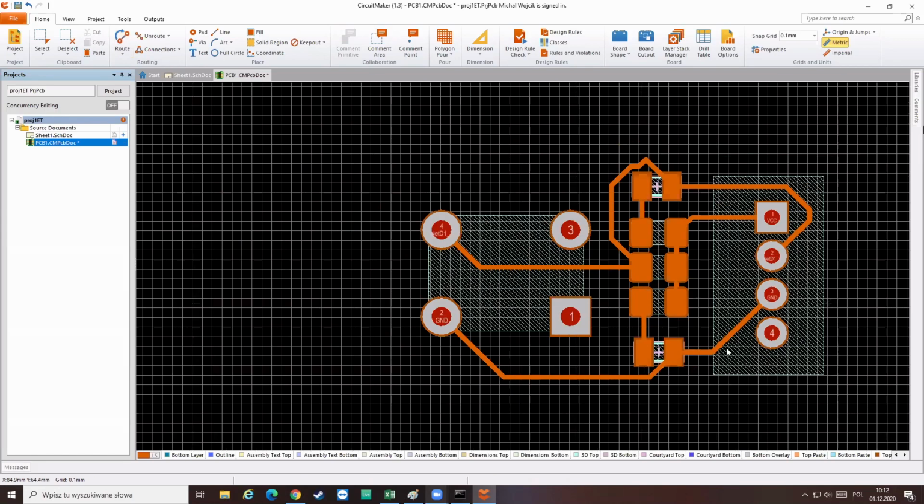Okay, let's say I have finished my PCB. No, of course not yet. Still, what we need is a border. And borders are usually made on a layer that is named keep out layer. So I'm selecting the keep out layer. Here I was at the top layer, and what layer you are already can be seen by the color here. So this orange is a top layer. I would like now to go to this purple keep out layer. And I would like to select the line. And let's make a line around the design.